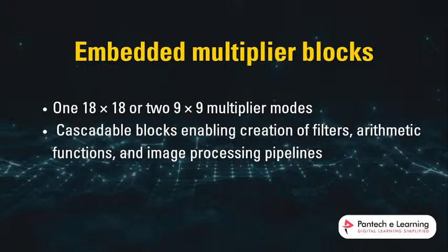And then coming to embedded multiplier blocks, our FPGA has multiplier modes like 18x18 and 9x9 and cascadable blocks, enabling the creation of filters, arithmetic functions and image processing pipelines.